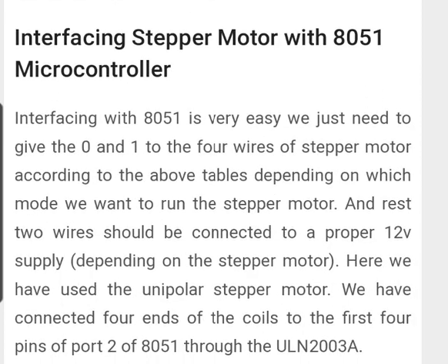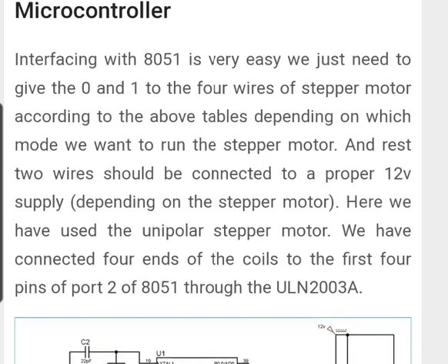Then the next is interfacing of stepper motor with 8051 microcontroller. Till now we have seen what is stepper motor, its modes and so on. Now the interfacing of stepper motor with 8051 microcontroller. Interfacing with 8051 is very easy. For that we just need to give the 0 and 1 to the 4 wires of the stepper motor according to the above tables, depending on which mode we want to run the stepper motor.